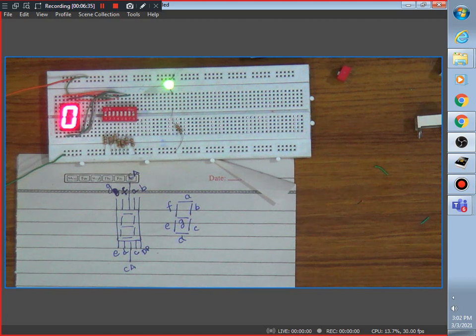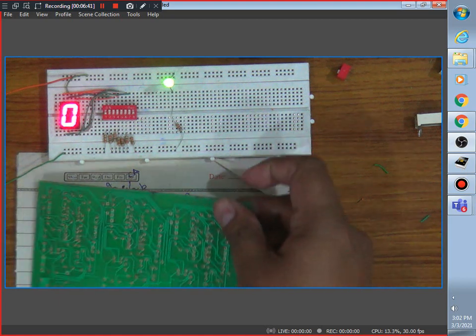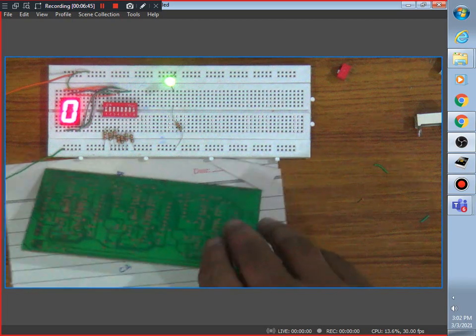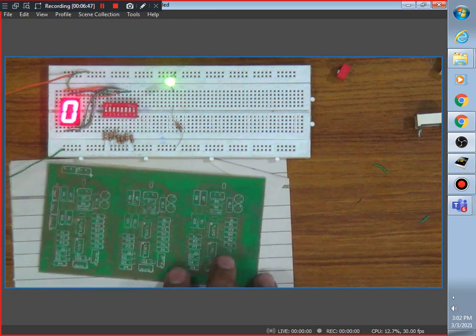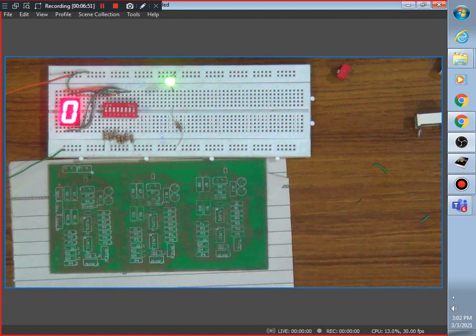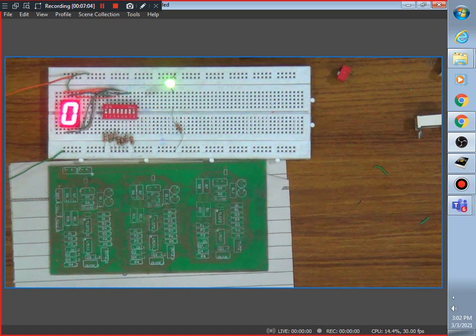I need a dip switch. Now, whenever you are going to physically put something on your PCB, and your PCB is looking something like this over here, you need some footprints. Now, what is the footprint? If you can see closely in this PCB, all these markings are actually the footprints of the components which are going to be placed on this PCB. I'm again repeating, all these markings are the part of that footprint on which you are going to place that component.